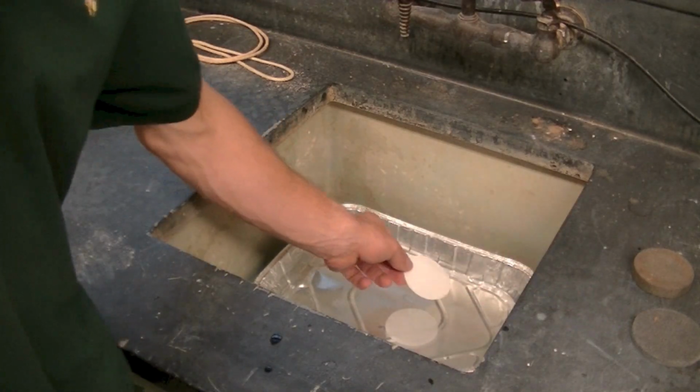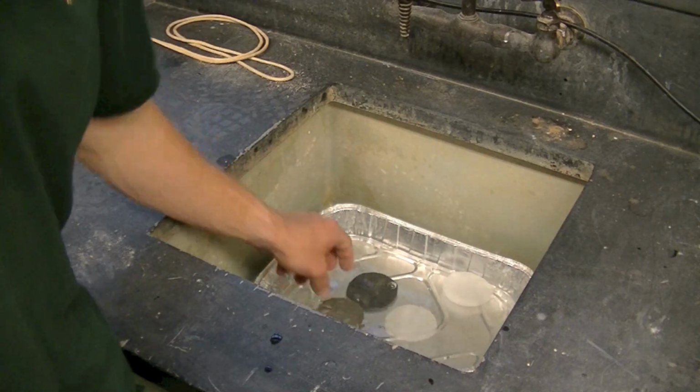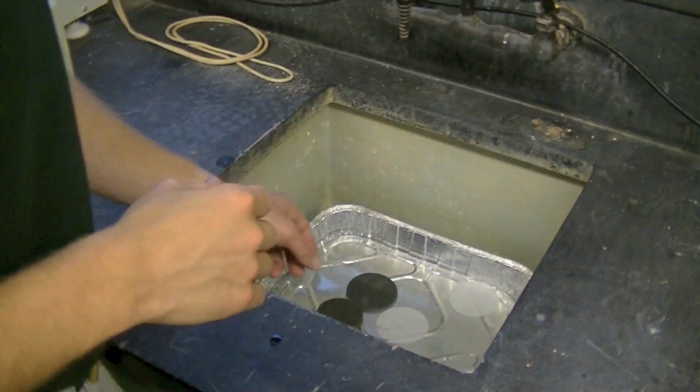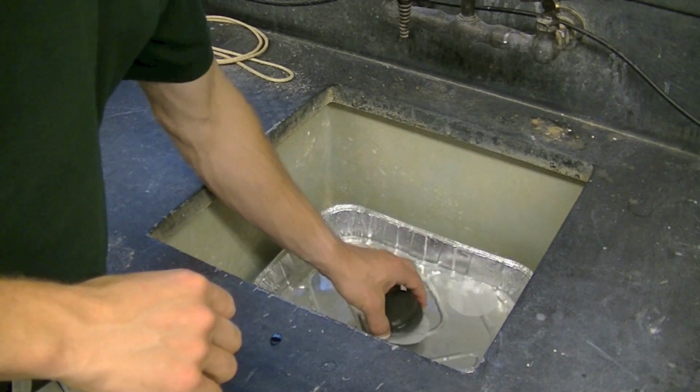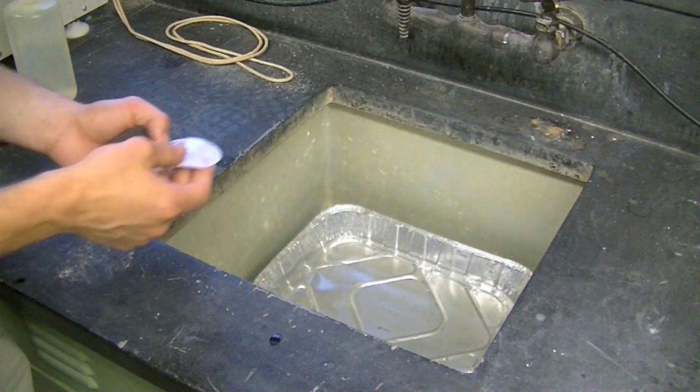Calibration for the consolidation test involves finding deflections of the porous stones and filter paper caused by the load. First, we soak the filter papers and porous stones in water for approximately 2 minutes. We strive to run the calibration just as we will the actual test. After 2 minutes, remove the porous stones and filter papers.